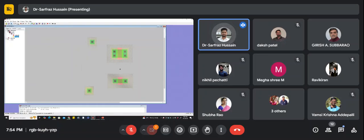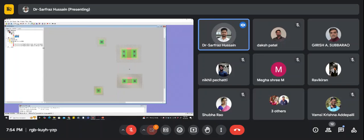Now at the initial stage, whenever you're doing the layout, make sure that you check for the errors with each connection. If you don't check for each connection, then later on it is very difficult. So whenever you're doing layout, you should check after doing each placement or each connection, you should actually check the DRC for errors.